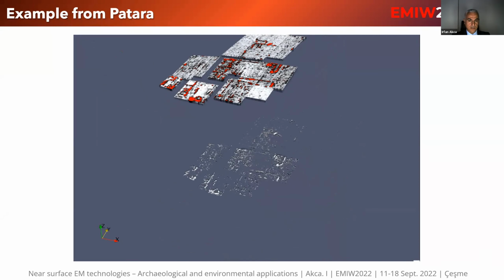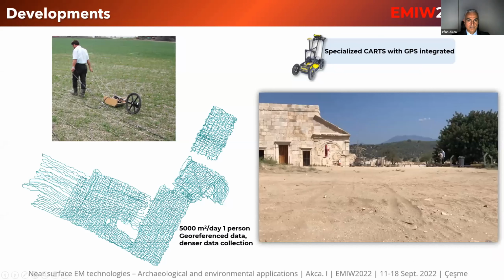As I already mentioned, for the measurement, for example using a 500 megahertz antenna, the trace length is just 100 nanoseconds, so you can measure a lot of traces in just a second. In some cases, the speed is controlled by the wheel you see here.